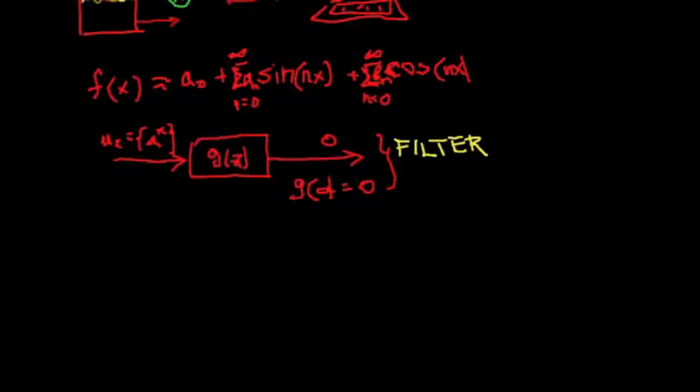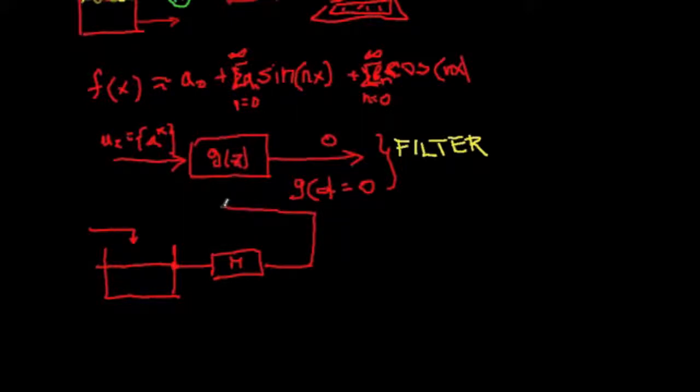In other words, for the previous model we have a simple control scheme, where we have a measurement, and if we don't have a filter, it goes directly into the controller feedback, and we feed this back into the height controller, which is this valve. If this height changes, the measurement device records that and sends it to the simple feedback mechanism that opens and closes this valve to regulate the height.